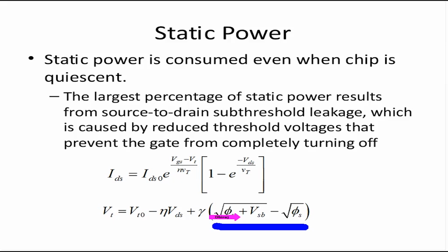So if you go back to the equations of PMOS and NMOS, the transistor equations, usually at the start of the understanding, we assume that VSB is 0, the body effect is 0, but you could have a case where the body voltage is not 0. So there will be some difference between the voltage at source and voltage at body. This takes care of that effect. This takes care of the drain to source; it depends on the drain to source voltage.